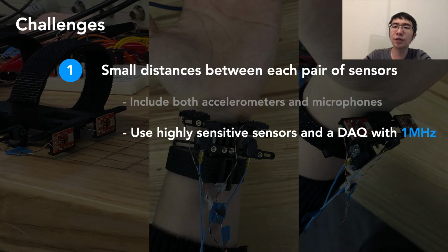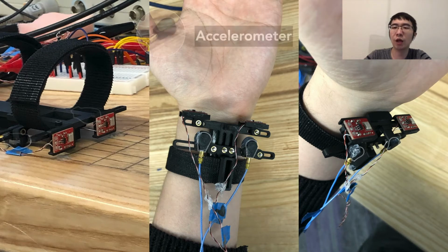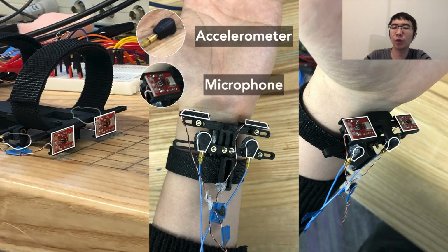And then, we also selected highly sensitive accelerometers and microphones in our wristband prototype and leveraged a DAC that can support as high as 1 MHz sampling rate. We use this custom hardware setup to capture the small time differences of arrival. Here's our wristband prototype. After testing many different types of acoustic sensors available on the market, we chose 2 accelerometers and 2 MEMS microphone breakouts that are most sensitive to the tap signals. 4 sensors are situated on the bottom of the wrist with a mechanical structure.